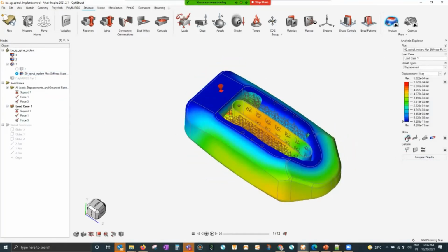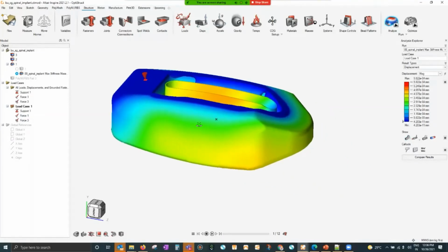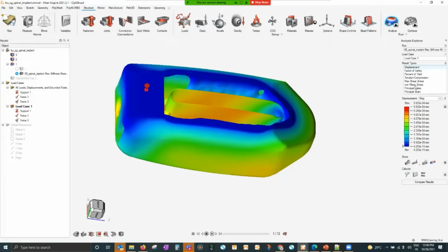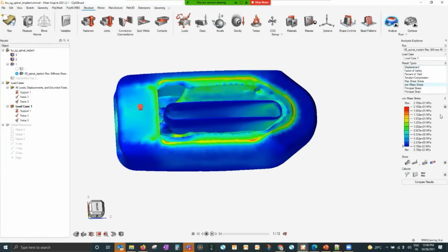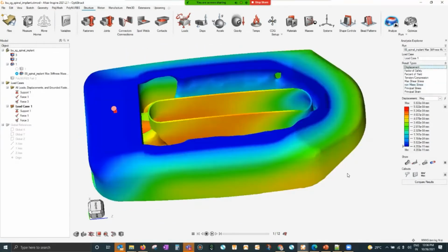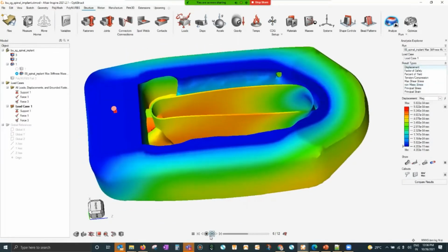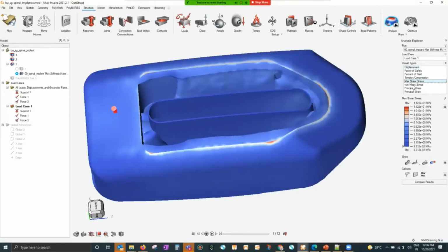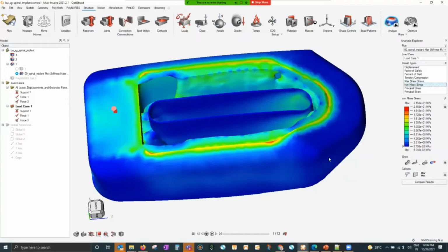You will see the result of the FEA. And in that FEA result, what you will understand is your stress and displacement, which is very critical. You will see that it is giving a max stress of 21 MPa, and you have displacement as well, and you can play animation as well to understand how things are behaving and so on. So this will give you the idea whether your optimized shape has the targeted, accepted values of your stress and displacement or not. So that thing we are confirming.